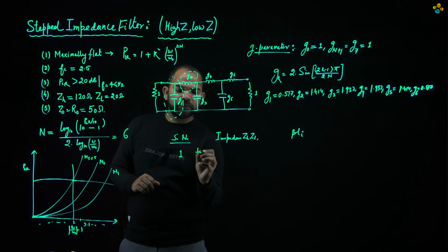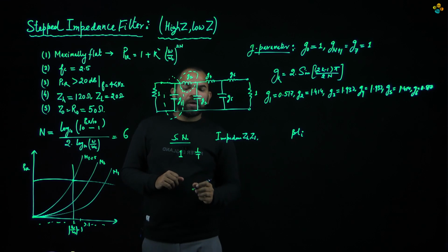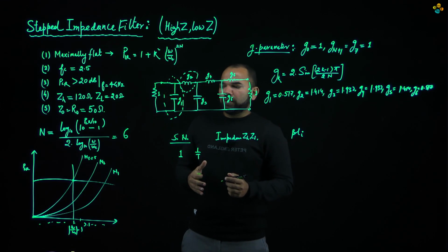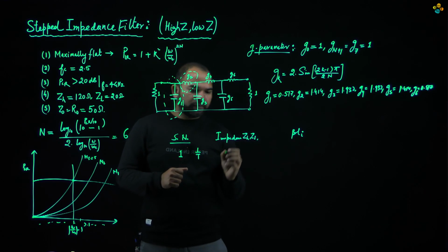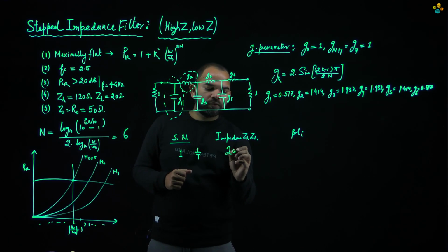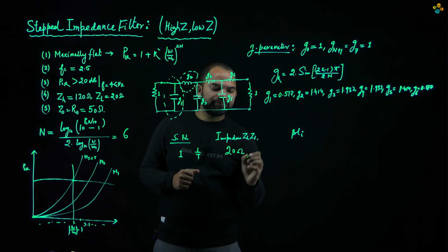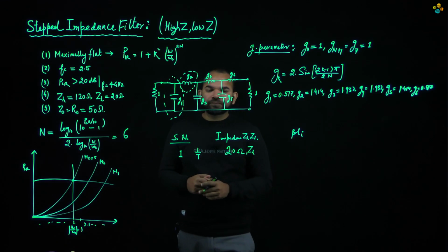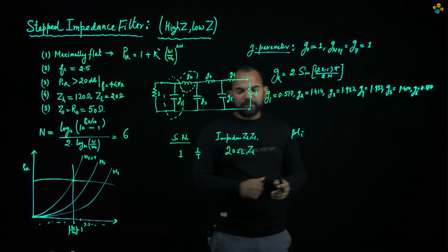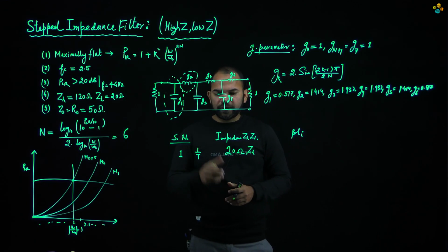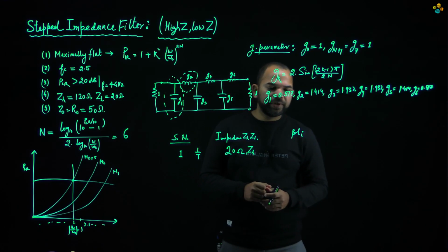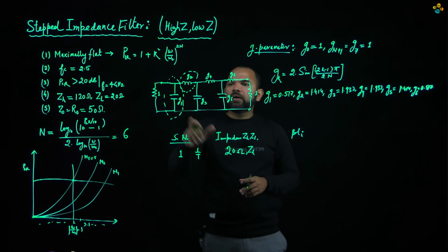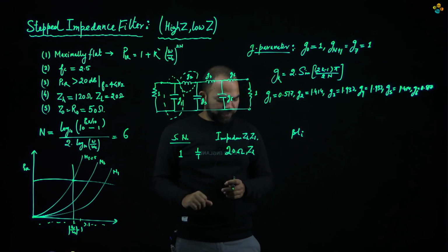Okay, so is it a capacitor? In the formulation, we have seen a capacitor can be replaced with a low impedance line. So low impedance line is 20 ohm for us, or we can write it as Z low if we want to design for some other low impedance value. And then we need to calculate the beta Li, say, how much is the electrical length for this capacitor.